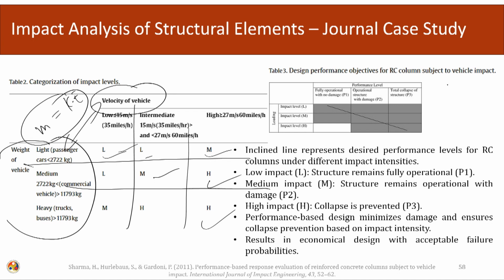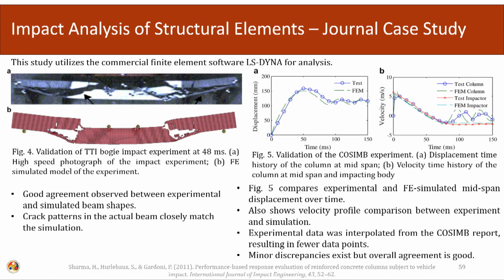Then we combine both of these phenomena, the demand side and the capacity side, and we determine the performance objective. Basically what we are trying to do here is calculate the limit state function. Upon doing that, we used LS-DYNA, which we discussed earlier, in order to simulate the impact event.